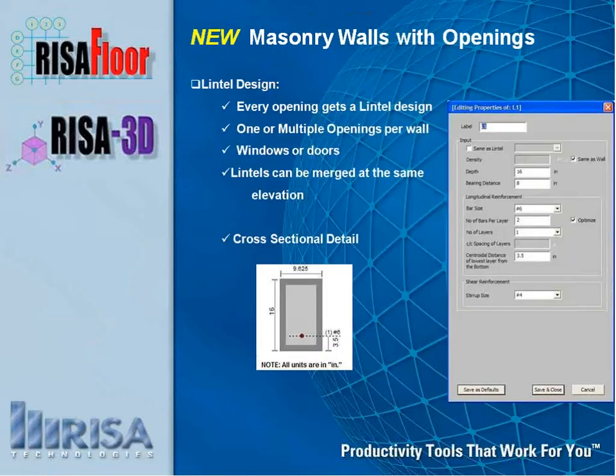Lintels are also designed for us in RISA 3D and RISA Floor. So every time we add an opening, a lintel gets placed above that opening. We can add one or more openings in a wall. They can be doors or windows, any size, rectangular shaped. And lintels can be merged. So if we have two lintels on the same elevation, we can actually merge them.